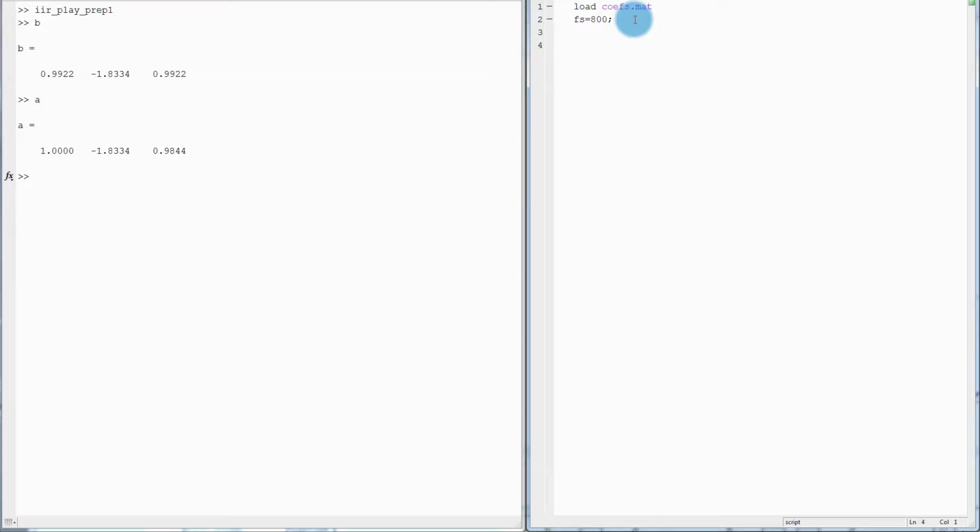So far you do not know how to compute the frequency characteristic of an IIR filter efficiently, but you know a way how to find the frequency characteristic of any filter. You just need to get its impulse response. And how do we get an impulse response of an IIR filter? Well, if I can implement that IIR filter in MATLAB, then I will just feed it a Dirac delta pulse and the result will be the impulse response.